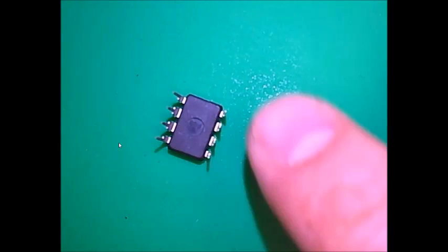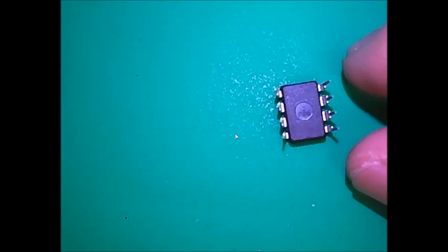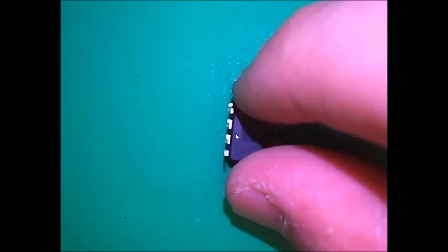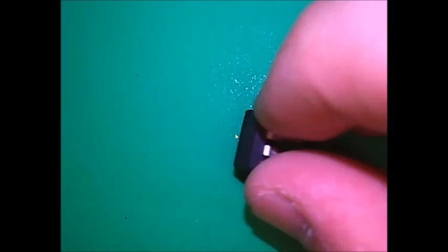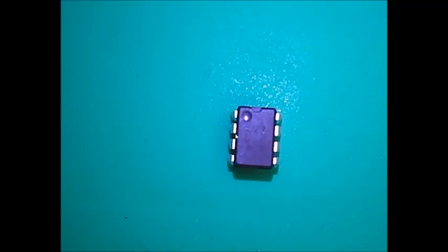Okay, so let's take a look at this one. These are the connections. This is to indicate which side is pin number 1, 2, 3, 4, 5, 6, 7, 8. So this is to indicate which side is 1 and 8, and which side is 4 and 5 over here. So you can see this chip is a lot bigger than the ones you see on the smartphone. On the smartphone, it is important to miniaturize or reduce the size of everything because of the limited real estate of the board.